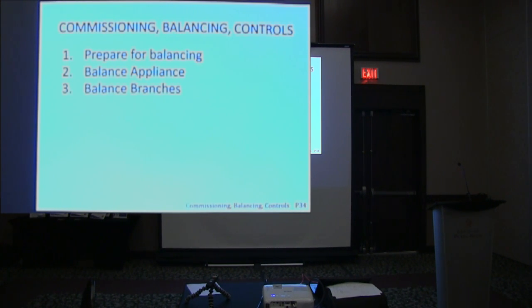On the design sheet, you say how much you're putting to where, and then on the installation and balancing sheet, you check off that it has what you designed. I think Doug's more asking, is it stuck to the unit somewhere, like a sticker or something? There's a sticker in every HRV or ERV that says what your balance is. Okay, good question.